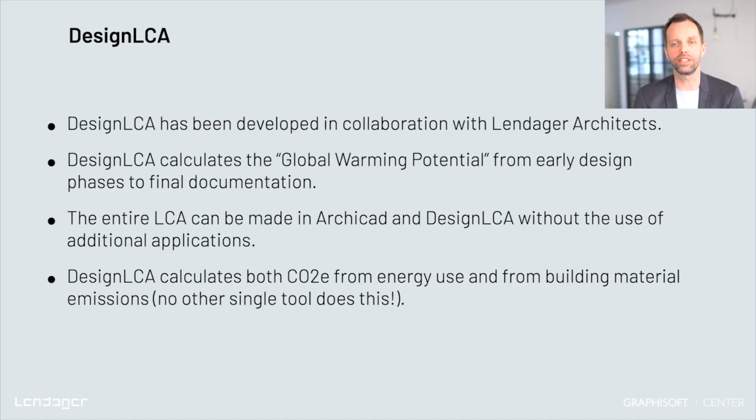The entire LCA can be done in Archicad with Design LCA. So you don't have to use other applications and you don't have to involve an engineer necessarily. And it calculates both the CO2 from materials and the CO2 from operations.